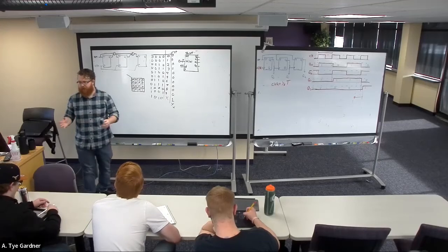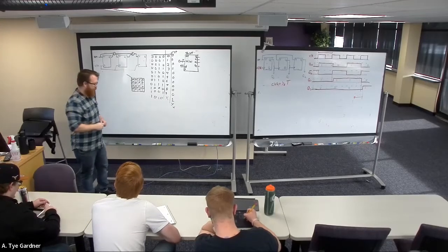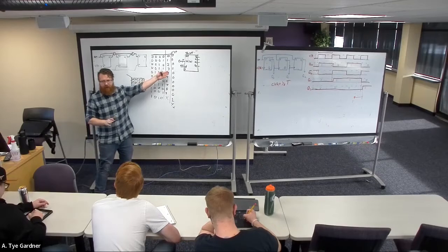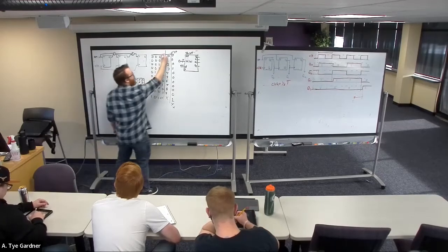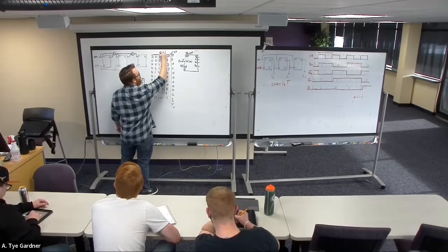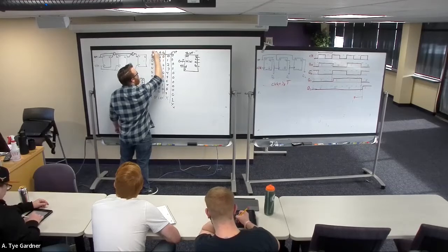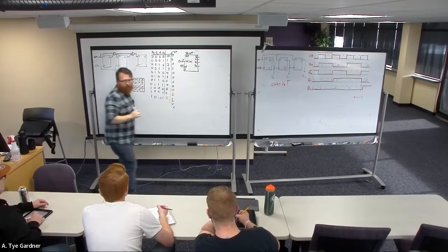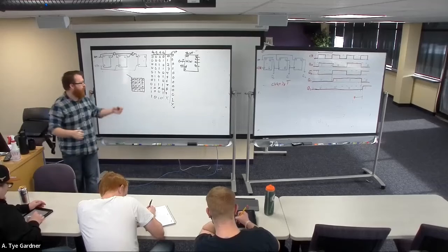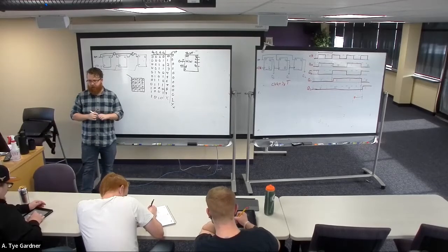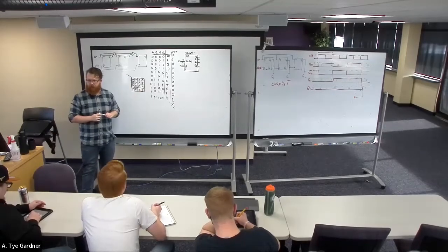That's our K-map for this circuit that we're building to make the reset signal. It's looking at the signals Q0, Q1, Q2, Q3 of this counter. That's its inputs. The output of the counter is the input to some combinational circuit that I want to design to do this reset for me.